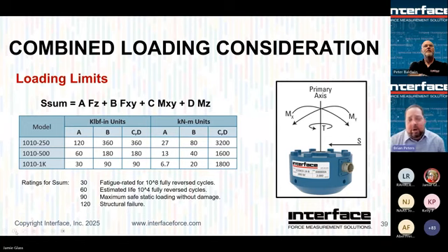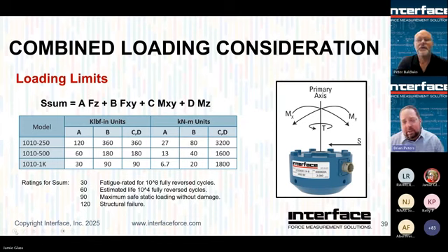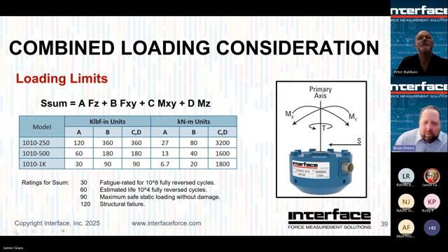That's great. But because we do this, because we have specs around this, we know exactly how the load cells can take other extraneous loads and how that's going to, A, impact the accuracy of the signal, or B, how it's going to impact the life of the sensor. So this table here on the left is a snippet from what we call our composite loading worksheet, which presents an equation that allows you to look at a calculated theoretical strain sum value, it's kind of unitless, as a function of your input loads.